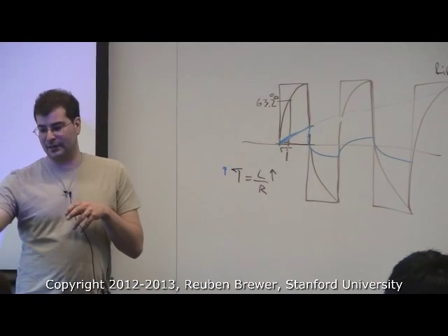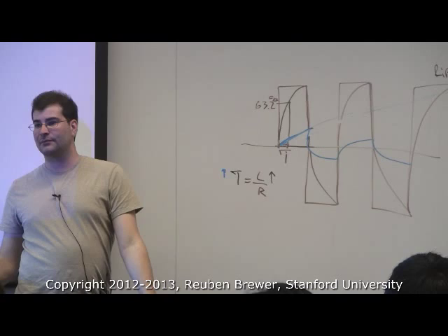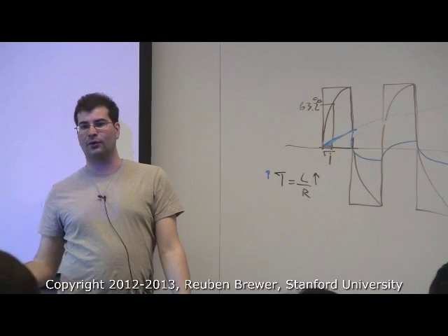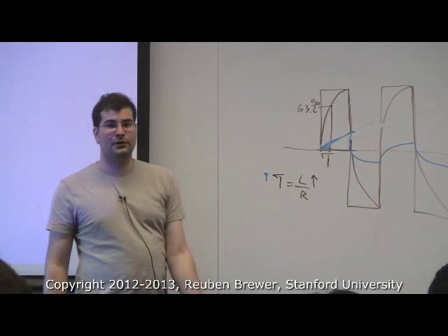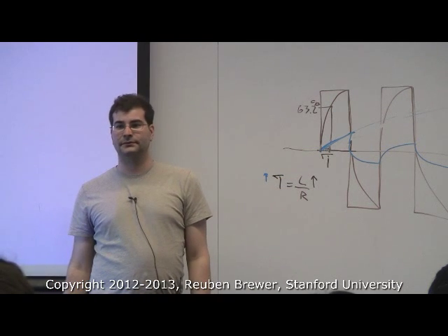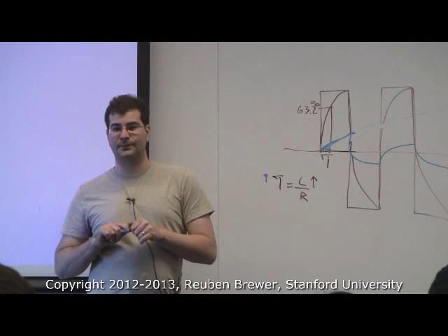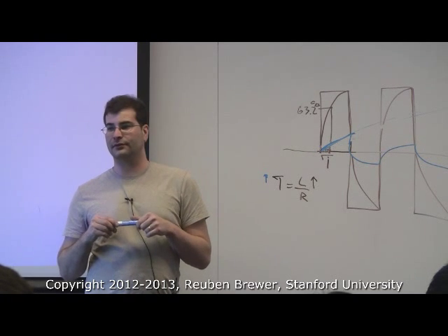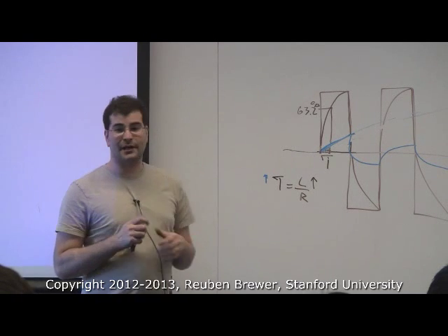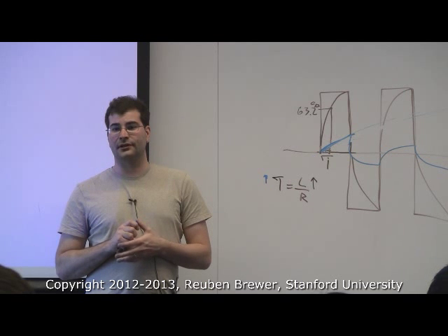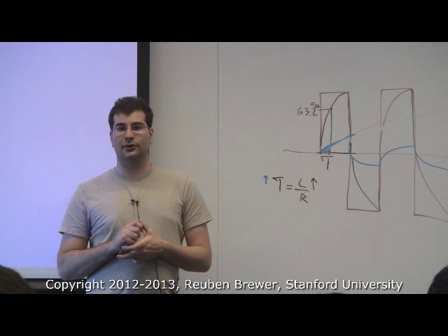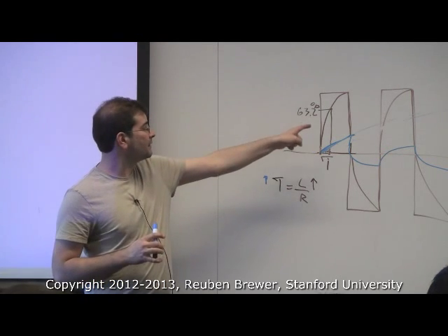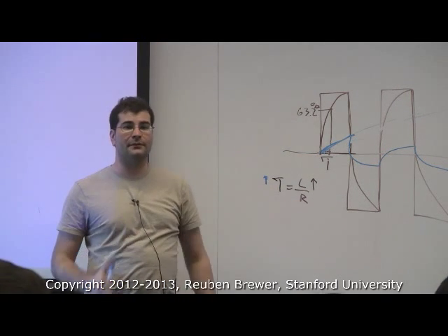If you took a Maxon motor and compared it to a non-Maxon motor of roughly the same torque or size, the inductance on a Maxon motor is insanely low for roughly the same resistance. What does that mean for the time constant? If the inductance is really low, the time constant is low, and then what does that mean in terms of this ripple current if the time constant is really low?